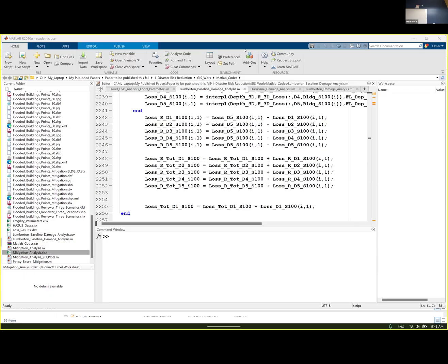So the first floor elevation is the only thing that is going to be different. It's a mitigation measure, but in terms of modeling, it is not going to take that much time. Why? Because our algorithm doesn't care about what you did here. Let's say this is our building, and our building is like 12 feet high from the ground, and you have to take a bunch of stairs like this. All I care about in this case is the FFE, right? If I have the FFE right, and the ground elevation right, and the water surface elevation right, that's it. You don't have to model anything. You just have to input the FFE, model the ground elevation, and model the water surface elevation. So in terms of mitigation, you don't have to do all this stuff.